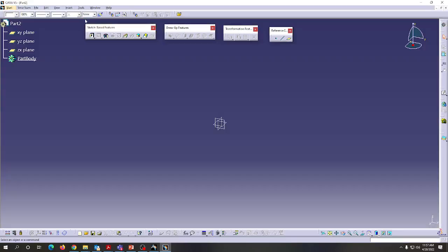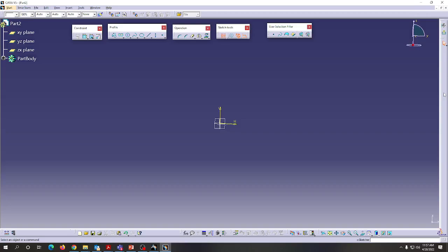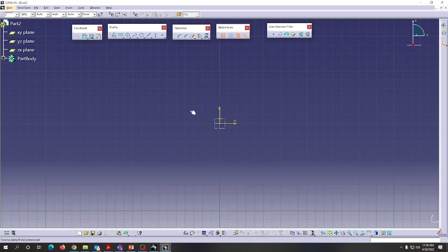After that I have to choose the plane. After I make it, I have to choose the plane, that is the YZ plane. First I'm choosing the YZ plane. Here also it is chosen with this color. Then I'm going to go with the sketcher toolbox. Here I have to click it over here. I have got the sketch toolbox. Now I'm going to make the drawing.